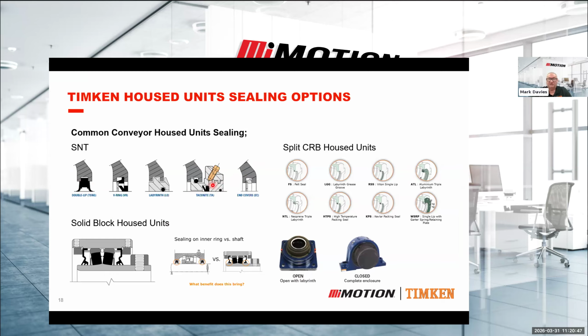It also gives you a purge, so you can push that contamination out with the fresh grease, and then gives you a physical seal, in this case a V-ring seal as well, which is a good option by most industry standards. That would be the most common type of seal on quarries and mine sites.